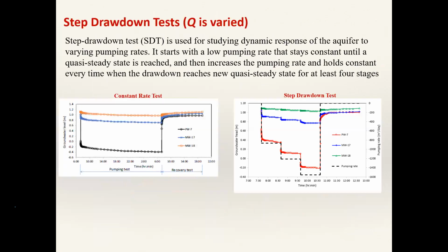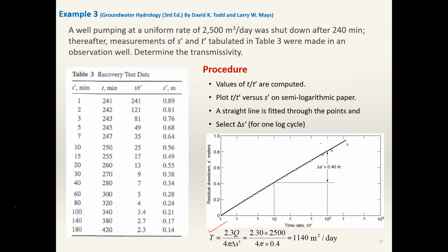But what is the limitation here? You can estimate only the transmissivity using the recovery test. You cannot estimate storativity. Cannot. Only transmissivity can be estimated. That is the limitation. So only transmissivity can be verified by using the recovery test.